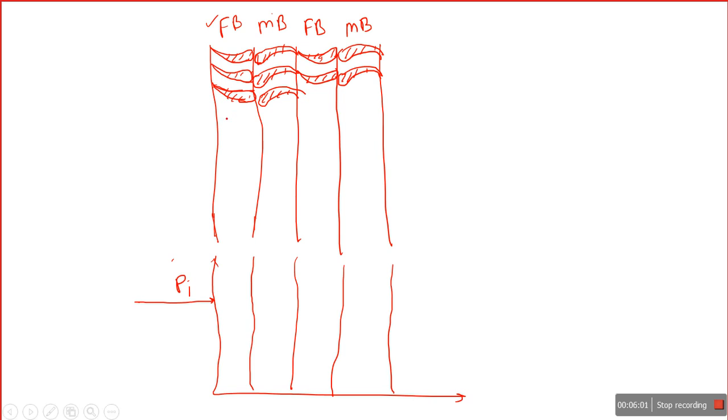When the steam is flowing through that fixed blade, I told you that the fixed blade acts as a nozzle. So we know the function of the nozzle: there is a drop in pressure. Now when that steam again flows through the moving blade, in case of an impulse turbine the pressure is constant because the cross sectional area between the blades is the same. But in case of reaction, the cross sectional area between the blades is varying, so again there is a drop in pressure.